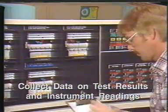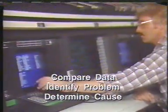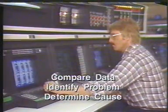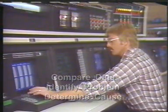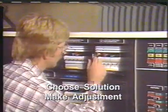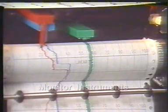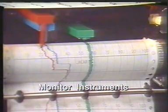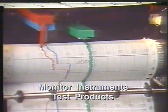The first thing an operator does is collect all data on current test results and instrument readings. Next, the operator compares current test results and instrument readings with previous data so he can correctly identify the problem. For any given problem, such as flooding, there may be several different causes. So in addition to identifying the problem, an operator must also determine what is causing it. Then the operator chooses the best way to solve the problem and makes an adjustment in tower operations to correct it. After an adjustment is made, an operator continually monitors instrument readings to make sure the situation is not getting worse. The tower is given time to adjust to the operating changes, and then new tests are run to see if the products are back on specification.